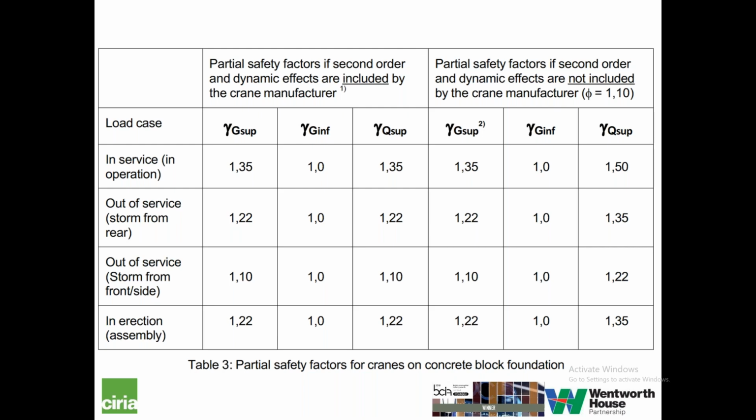You can see that they vary quite a lot from 1.0, well no, that's for a load which is resisting your overturning moments, as opposed to a load which is contributing to them, which has a positive factor of 1.5 or 1.35.